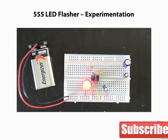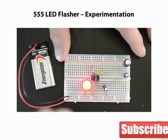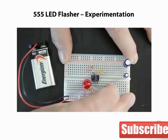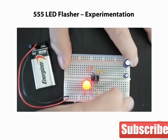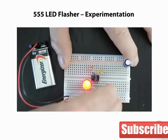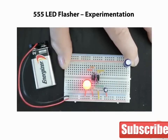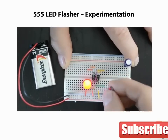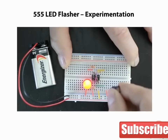Here we have an actual circuit operating here with all the components as specified with the 10 microfarad capacitor. Let's try and change the 10 microfarad capacitor for the 1 microfarad. We see after swapping it that indeed the LED does flash a lot quicker. Let's try it with the 100 microfarad capacitor.